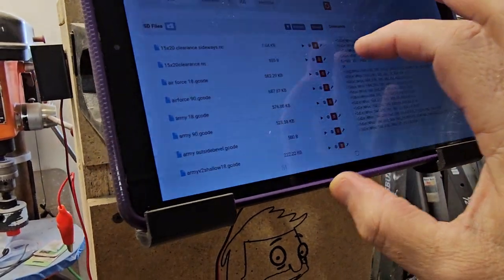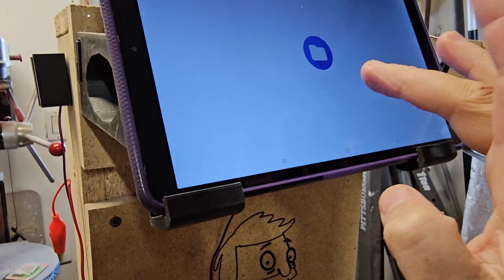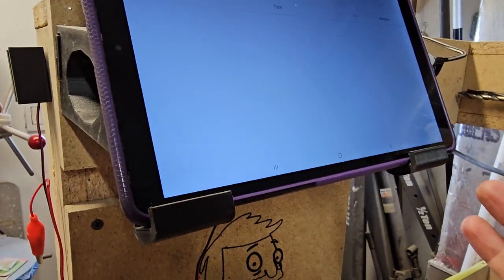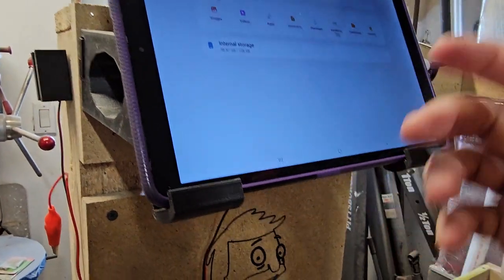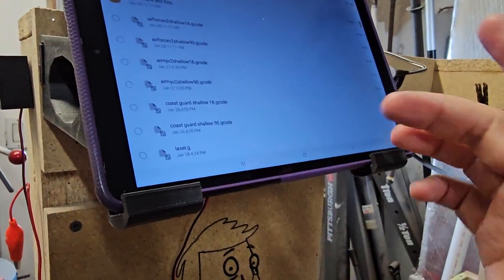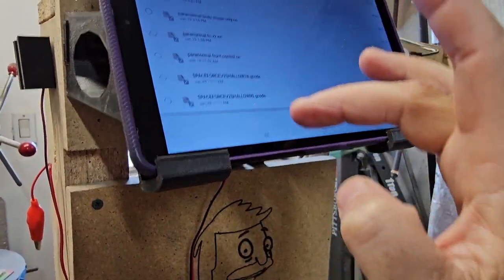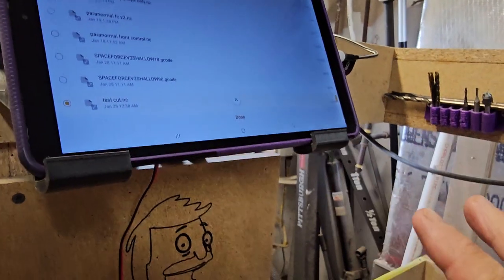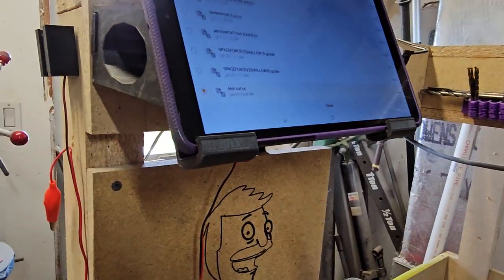Software-wise, we want to actually upload a file. So the Jackpot board runs kind of like a 3D printer. Yours may be running that if you're hooked into a computer, feeds every line of G-code to it. The old X-Carve that I was using before, that's the way that it was. Everything was actually run by the computer. It controlled everything. So it fed every single line of G-code, kept track of everything. It was actually pretty nice.